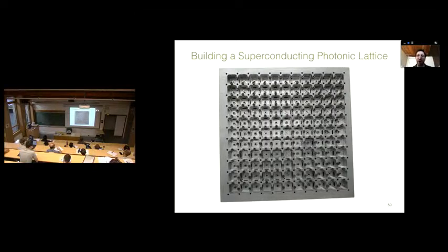I hope I've given you a flavor of how you engineer this connectivity with a real space rotation. What I'd like to talk to you about next is how to actually break time reversal symmetry in a topological circuit. Here we'll do it in an array of microwave cavities. This should give you a flavor of how to make lattices for microwave photons and how to engineer a real, honest-to-God time reversal breaking Berry flux. But before we go on, are there questions on this piece?